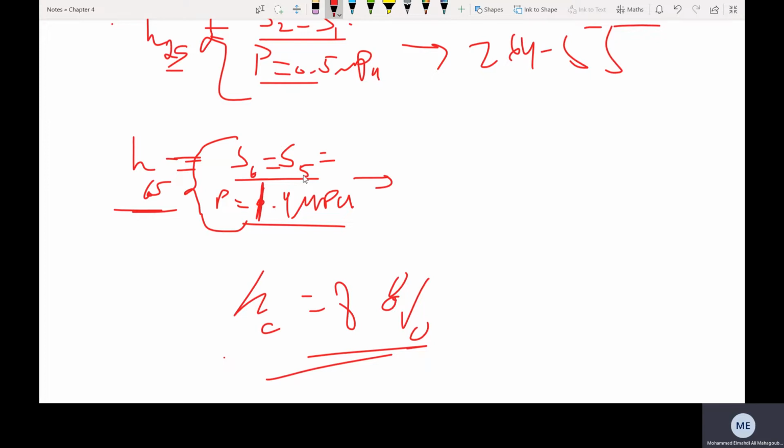1,400, because that's the uppermost pressure. So 0.91, that's where the Sg is equal to 0.91, which is clearly less than my S, so it is superheated.